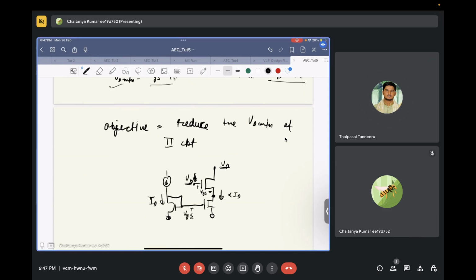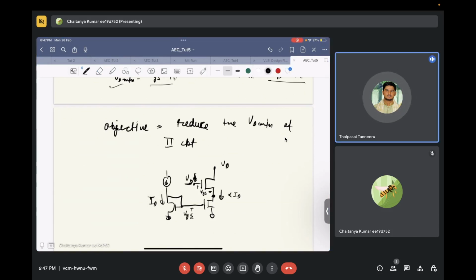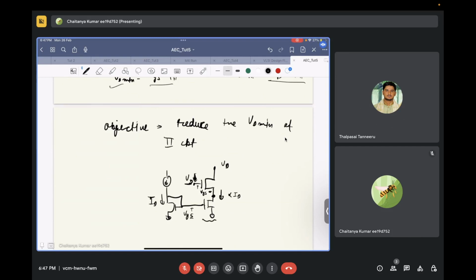No, how is it VD? The gate voltage is VG, so VD should be VG minus VTH, sir. Yes, VD min of the lower transistor, you mean, right? Yes, sir. It can be VGS minus VTH. Okay, so if this voltage can go minimum up to VGS minus VTH,